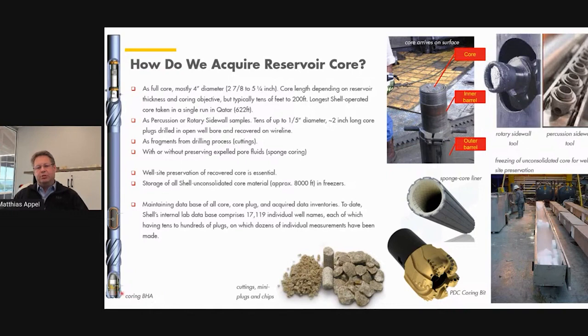And the coring borehole assembly is comprised of basically two concentric tubes. One strong outer barrel, as we call it, which conveys the pressure and forces and rotation. And within that outer barrel is an inner barrel, that is separated from the outer barrel by two bearing assemblies on the top and on the bottom, so that when the outer barrel is rotating, the inner barrel remains stationary. And now you can imagine with that hollow donut bit, if you're drilling to the formation, a cylinder of the formation will remain undisturbed, kind of undisturbed at least, and will rise inside that inner barrel and can then be